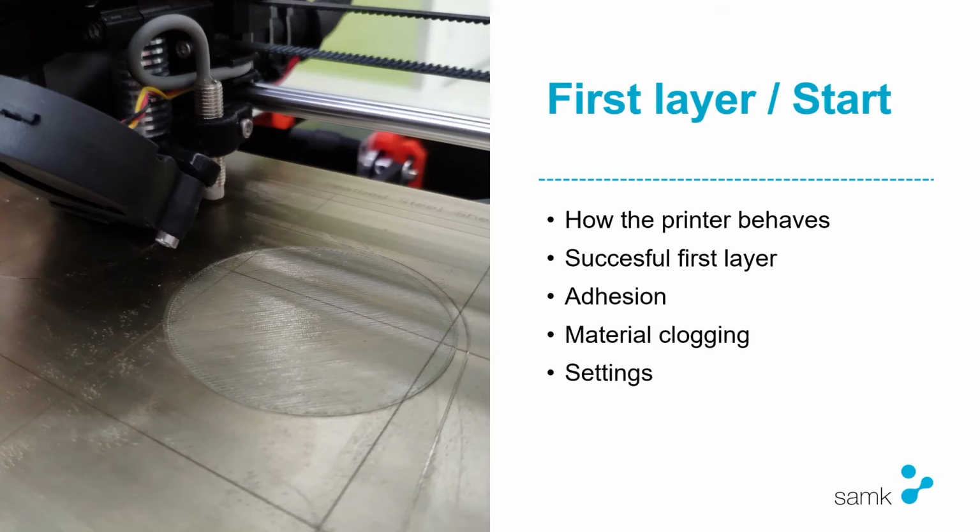And you will see also any material clogging issues on the first layer. If the nozzle is too low, it will start to clog the extrusion completely. Or if there's some leftover material from the last time you printed a material that needs higher temperature, you will notice that too. And you will see, of course, your settings if you forgot your supports.